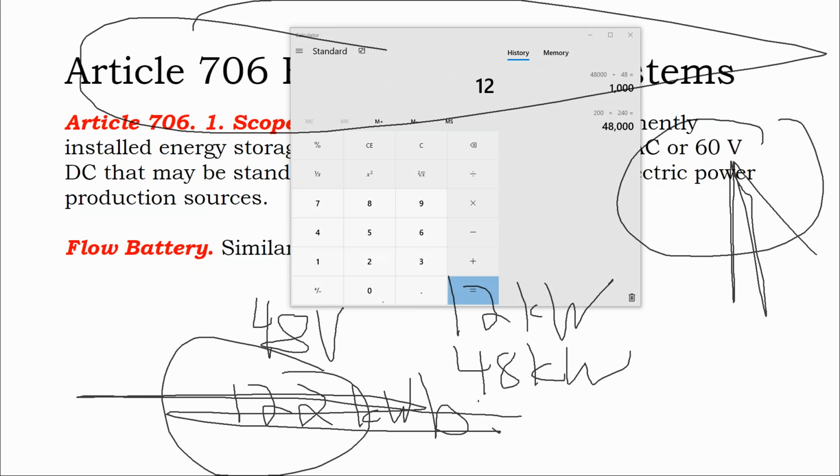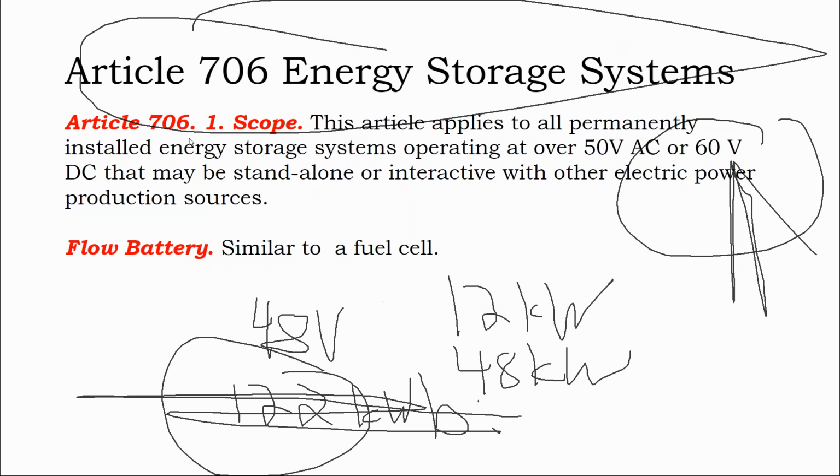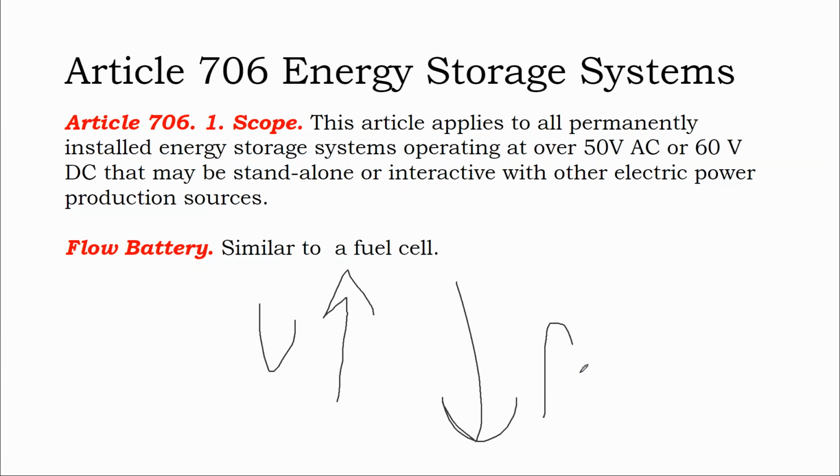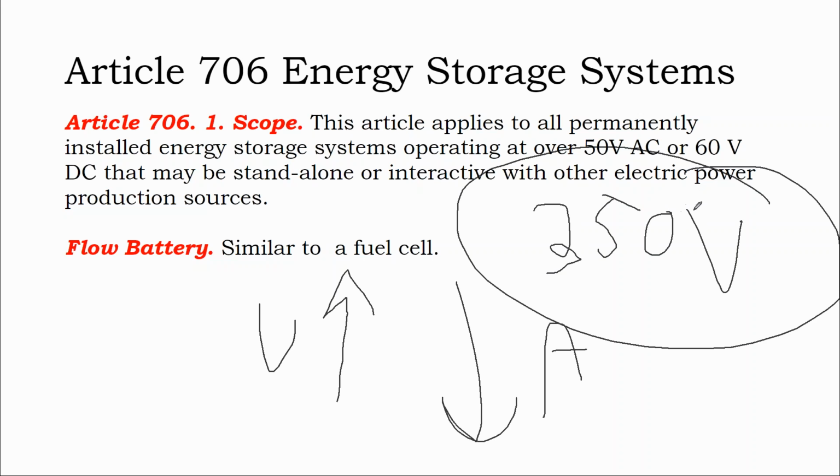So what is safer and more cost effective is to increase voltage and decrease amperage. With the Tesla battery and other battery inverters made specifically for lithium ion, and in electric vehicles for that matter, you see a move towards something like a 350 volt platform.